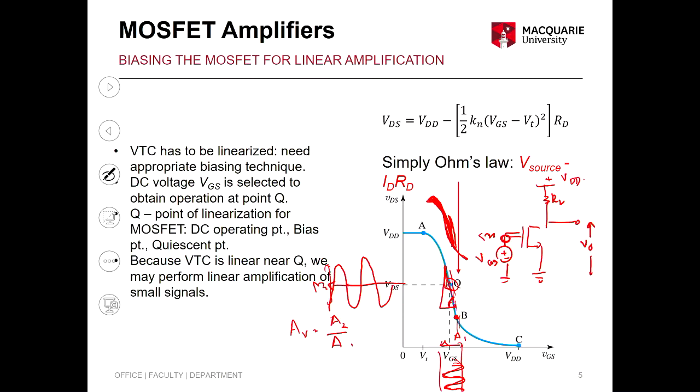So there are different types of amplifiers. One is called a high power amplifier. High power amplifiers tend to operate towards the bottom, okay? Because you need to bias. So this gives you what voltage you should bias your circuit. So your VGS here could be, say this is 2 volt, and that's 0.7 volt. So you could bias at 1 volt, you could bias at 1.5 volt.